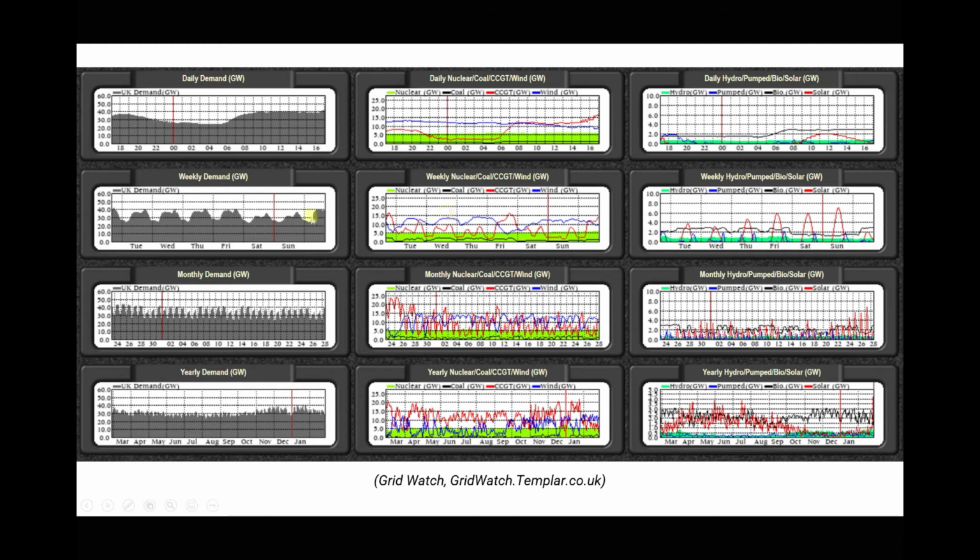If we look at our second graph then, where we have these definite spikes at around 5 p.m. each day, how is that demand being met? Well, it's being met in part by our combined cycle gas turbines, but when demand is particularly high, we have another alternative. Over here on the right-hand side, we have pumped hydroelectric storage plants.